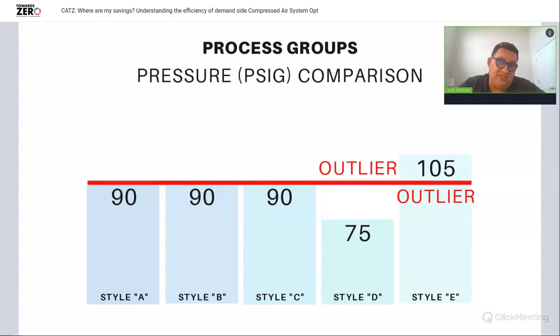But what the manuals didn't say is that internal to the 6 or 8 processes that required that pressure was a regulator down to 72.5 PSI, and that then went to a pneumatic amplifier to 145. So the entire time, the customer was pressurizing their entire facility to 145 PSI and buying 145 PSI rated compressors when they just didn't need it.